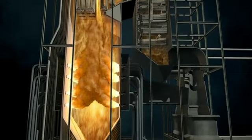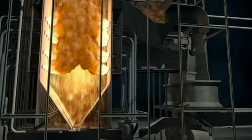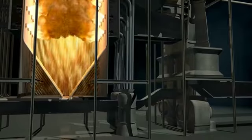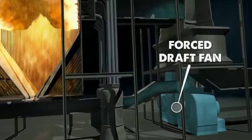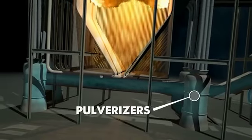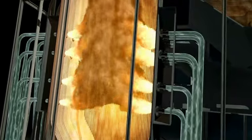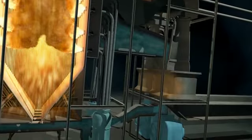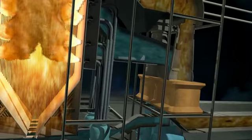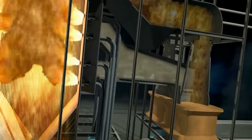Today's boilers, as they have been since their origin, involve the complex production and manipulation of steam. The forced draft fan blows air into the system. A portion is routed to the pulverizers, which crush coal into a fine dust before pushing the mixture up through feeder tubes. The other portion passes through an air preheater, which transfers heat from the exhaust gases to the incoming air, raising the air temperature, reducing moisture, and producing a cleaner burn.